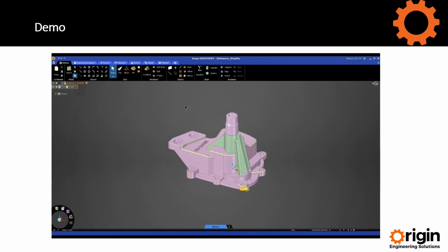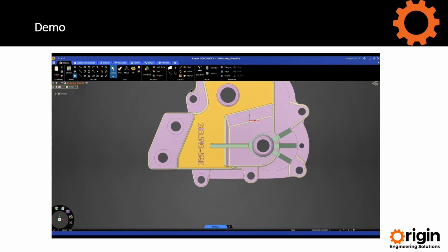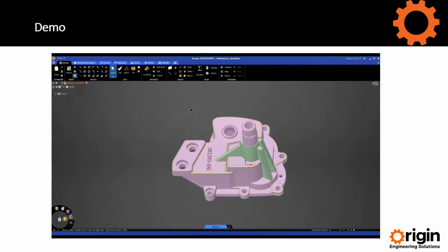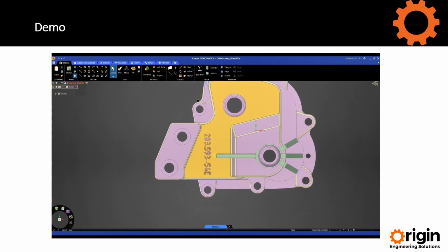A lot of the time, if you are meshing a model, you might want to refine your model a little bit, remove small faces, especially embossing and engraving, or you actually might want to change your model in some way. So we have tools to do all that sort of thing. For example, in this model, I can clearly see there's a bit of embossing and engraving. In the explore mode, we don't actually need to defeature anything. We would be able to run a simulation on this model. But if you wanted to go into refine mode and make sure you don't have any mesh issues, you might want to start removing things that aren't really necessary for the simulation.